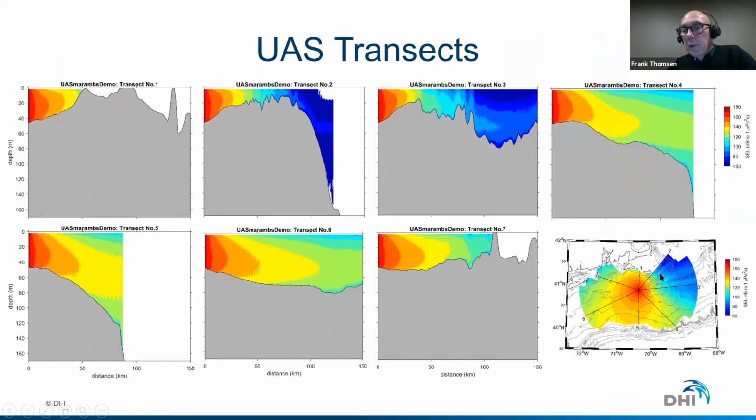If you look at this noise map in the lower right area here, you can see the sound source in the middle. This is the Baltic area, an area where there are wind farms being planned. And this is pretty much in the middle of the Polish Baltic area. And we model cutting these slices through the bathymetry, which we call transects. And then we model the sound transmission loss at each given transect. And I would like to show two of these transects in more detail.